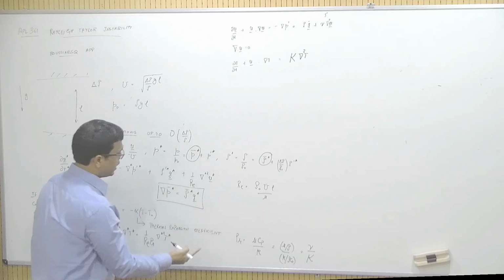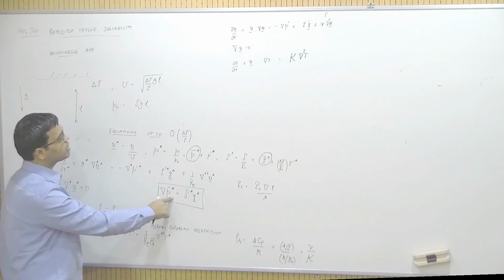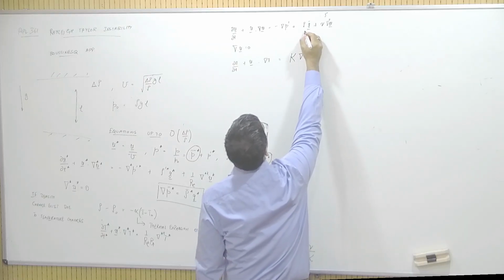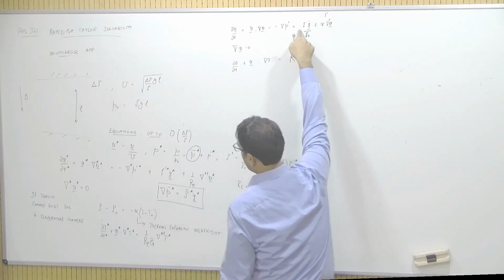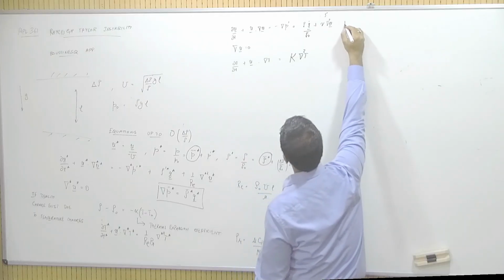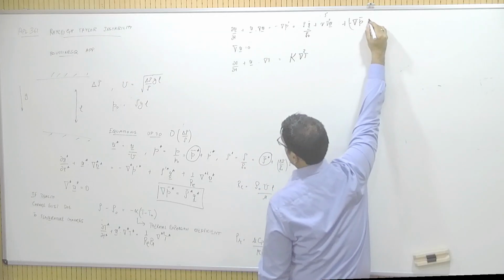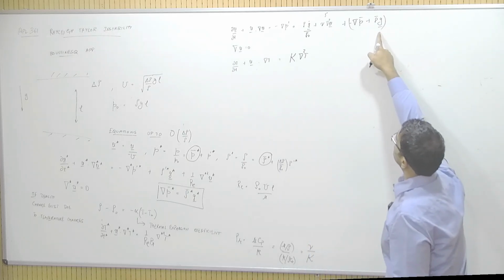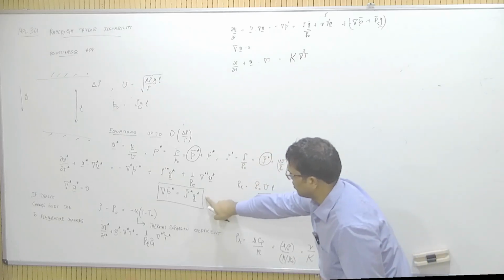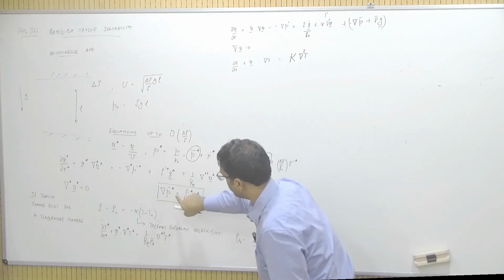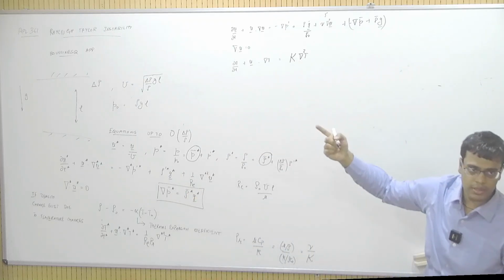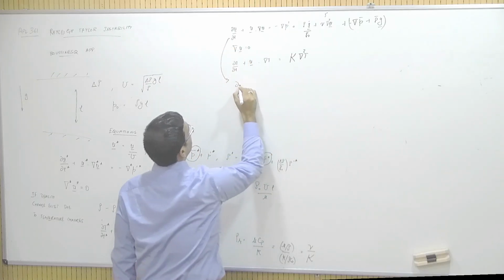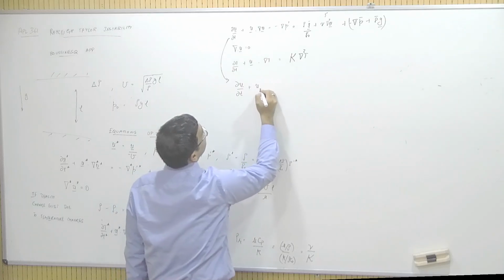So what I can do is again dimensionalize this, and here actually you will get a rho by rho naught. And I can dimensionalize this and add this quantity. The reason I am adding this quantity is because this is basically 0. You convert this into dimensional form, you will get grad P bar equals rho bar G, and I'm just adding a 0 on the right hand side. The reason I do this is because then I can write my momentum equation as this.